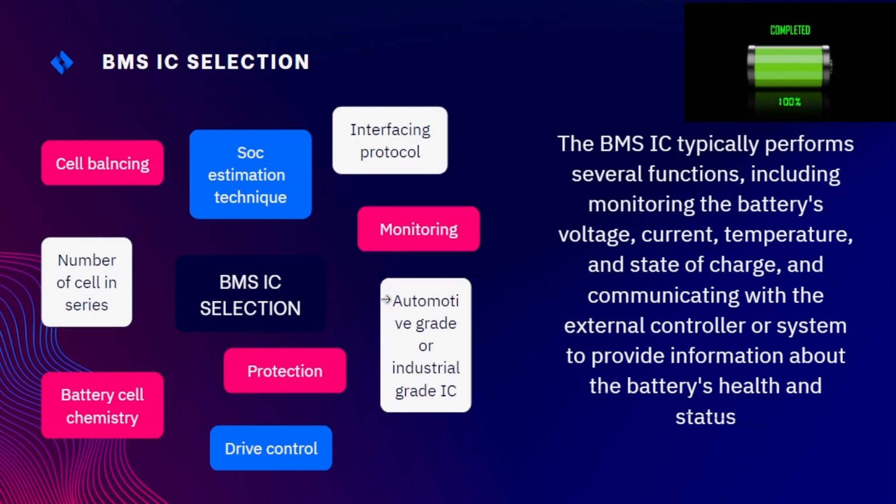Next one is fault detection. Another important consideration is fault detection. If it detects a fault in the system, do you want simply an alert that a fault has occurred, or do you require more advanced functionalities, detecting the fault and then implementing system changes such as an automatic shutdown? Some BMS ICs simply detect faults, while others can detect a fault and implement system responses to react to the fault.